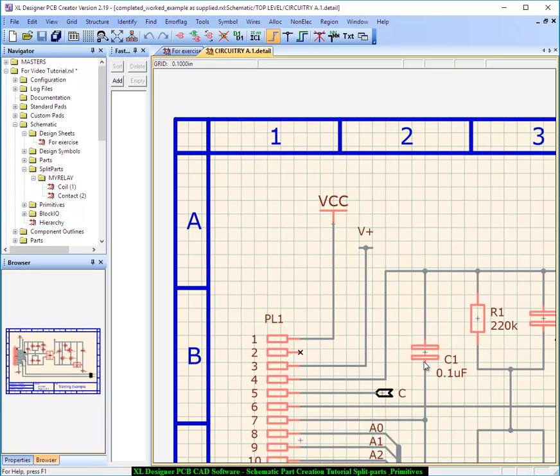The advantage of using a signal name primitive is that you don't have to spend any time typing in the signal names, which might lead to typing errors, and it makes the schematic easier to read. When the parts and wiring list is extracted in flattened mode, then all like named signal names are automatically joined to one another across sheets without you having to do anything.